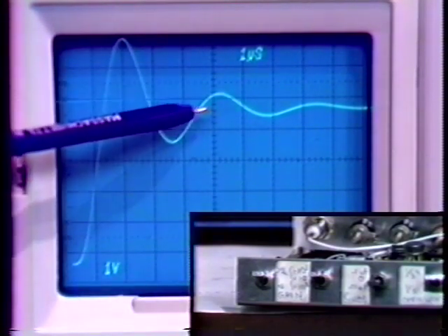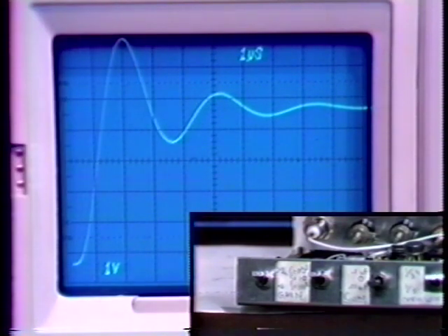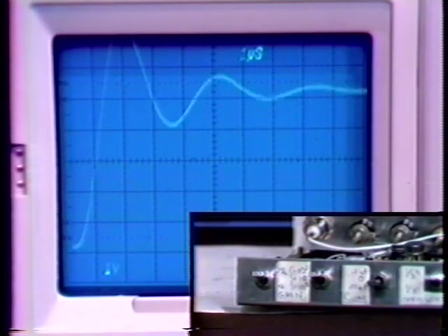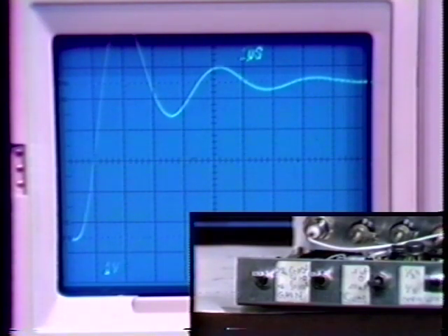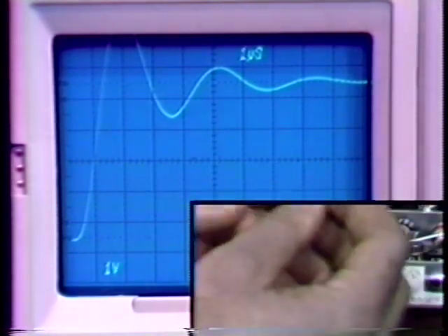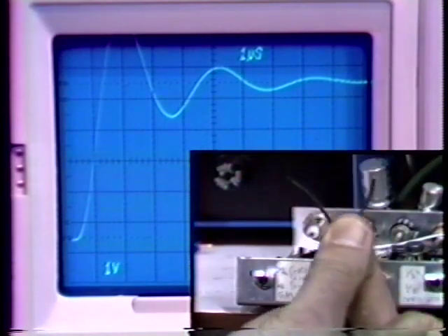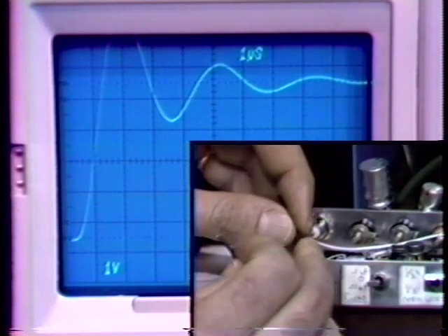Reasonably high frequency ringing at about 300 kilohertz. We have 1 microsecond per division horizontally now. So let's see if we can compensate that. If we really believed our numbers, we'd conclude that we needed 20 picofarads divided by 1,000, and that seems somewhat unrealistic. Actually, we need a capacitor a little bit larger than that. But let's get our capacitor this way. I simply have 2 pieces of wire that I'll put into the compensating terminals.